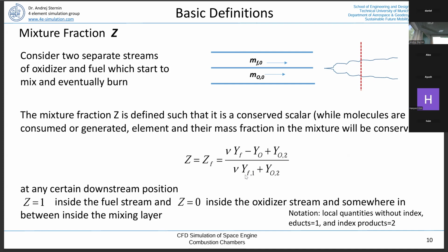The reason is we raise the temperature due to the heat release, and raising the temperature is also increasing viscosity, and increased viscosity is in principle damping the turbulence. So a large number of early combustion models say, okay, temperature increase, there is no turbulence generated by chemical reaction, turbulence is damped by chemical reaction.